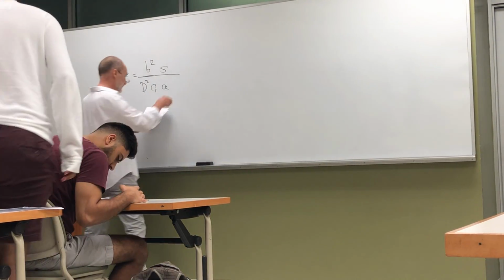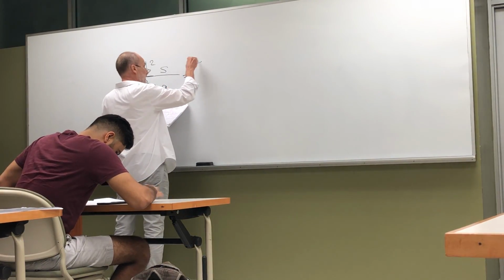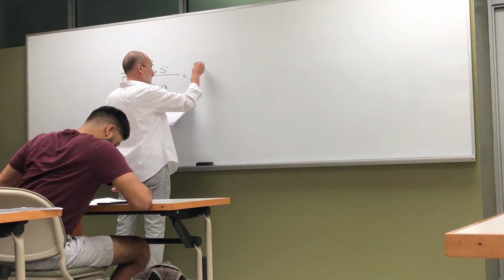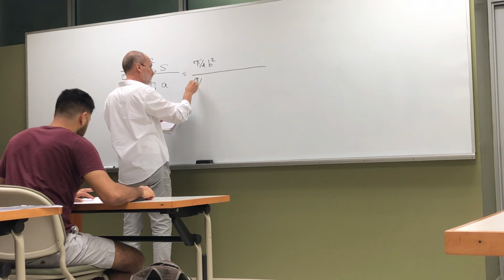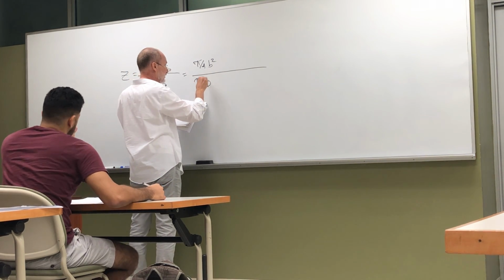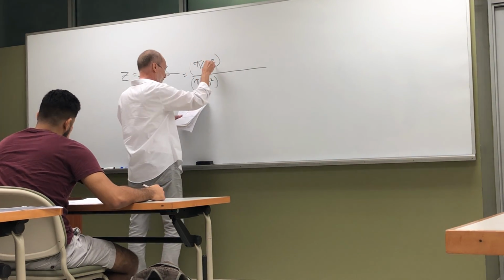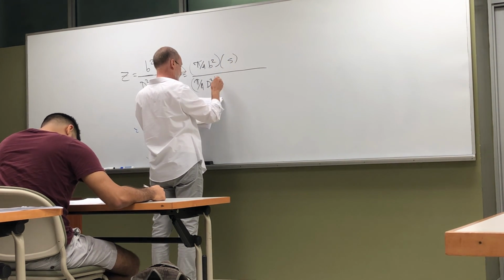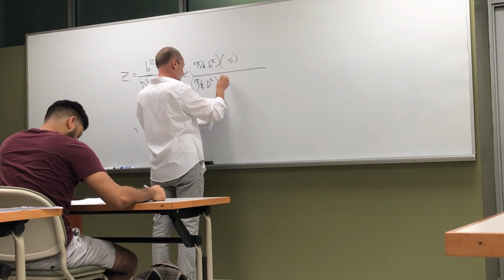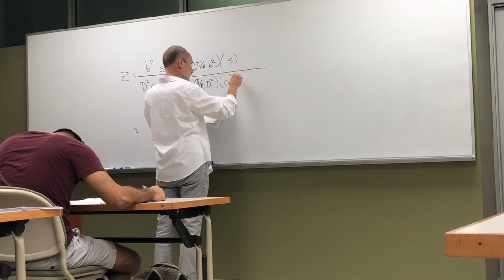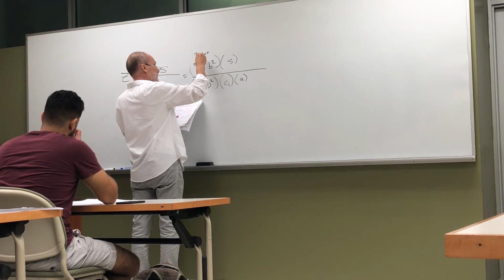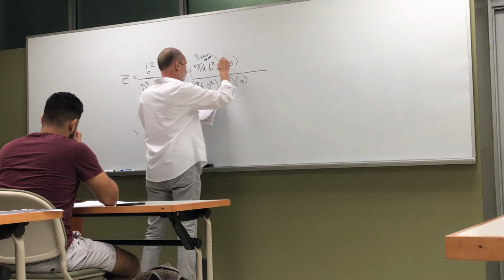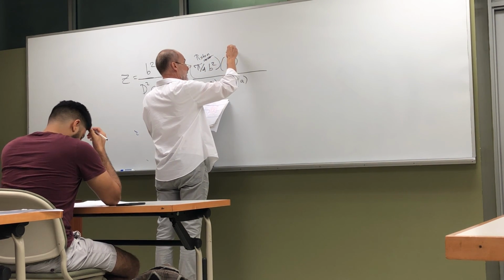But physically what we've got here is, if I multiply both sides times pi over 4, which eventually would cancel out, and here's, see, flow coefficient A, this is piston area, and this is mean piston speed.